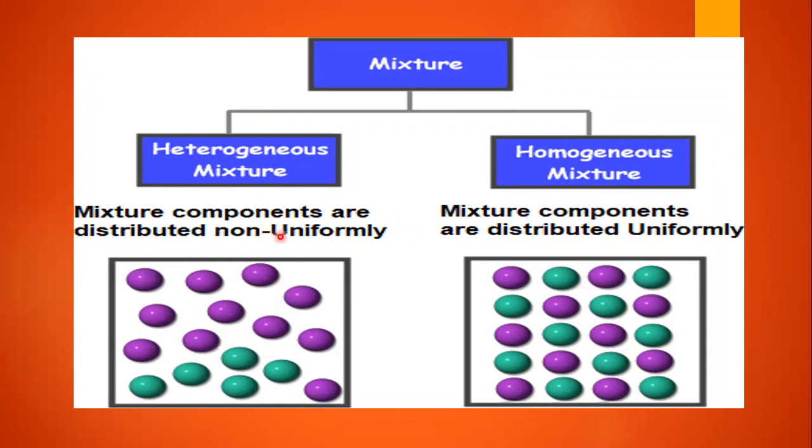Because of the high compression ratio, the pressure and temperature attained are very high, around 70 to 80 bar. Temperatures are around 600 to 700 Kelvin at the start of combustion, and almost 2000 Kelvin is reached at the end of combustion.